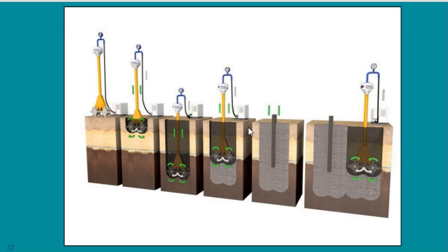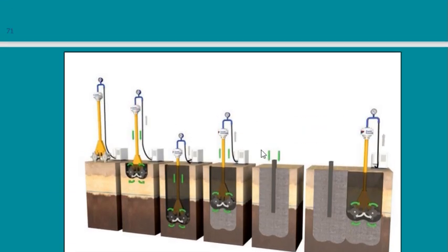So it will create a gap in the soil and touch the wall to the left and touch the wall to the right and drill inside them also. So when I construct the wall in between, it will be connected to the previous wall and the next wall. So finally, when I finish, I will find that I just did not have rectangular sections.